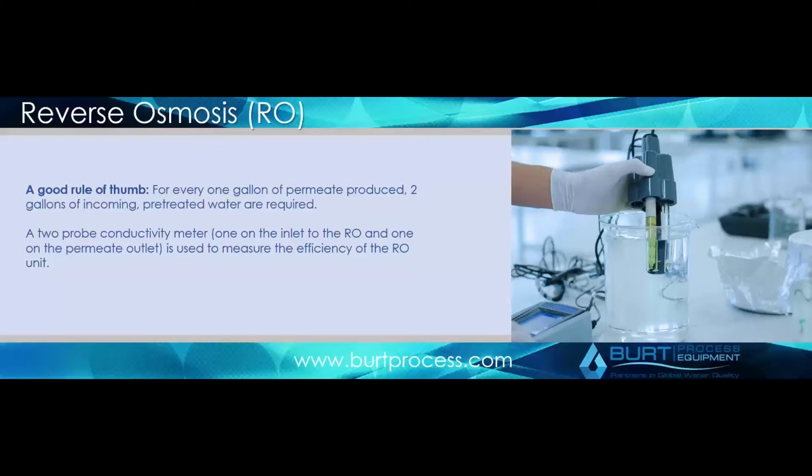One of the things you'll see, and anybody who's familiar with them, is that a lot of times people will advertise off-the-shelf RO units. People do make standard packages of ROs in the relatively small range, say half a gallon a minute to say 10 to 15 gallons per minute. And they're always rated at 70 degrees Fahrenheit. A lot of people also, I've heard people say, I want to use a thermostatic mixing valve, or I actually want to boost the temperature of the water to put it through the RO membrane. And there are pros and cons of doing both of that.